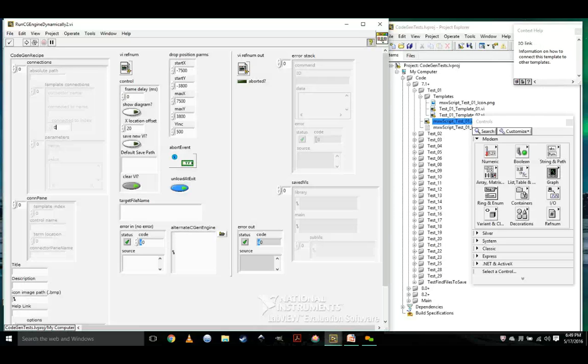So say I want to connect an error wire on template 1 to an error wire on template 0, I would go error in on connector name, and then connected to name is error out, and then template connected to index is 0. The template number is the index in the connections array.